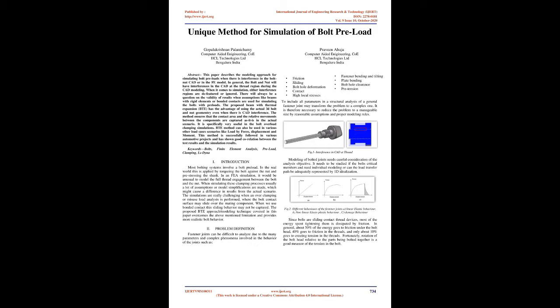BTE method can also be used in various other load cases scenarios like load by force, displacement, and moment. This method is successfully followed in various automotive projects and has shown good correlation between the test results and the simulation results. Keywords: bolts, finite element analysis, preload, clamping, LS-DYNA.